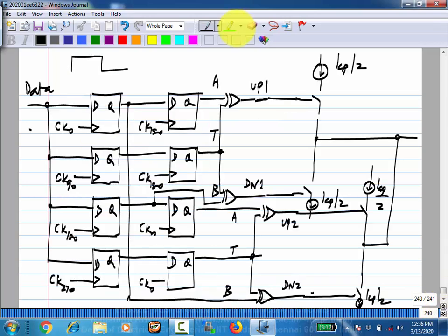Now, if you want to do the logical combination, for instance, if you want to see if up 1 and down 2 are high, you don't want to do anything and use a single charge pump circuit, right? Then you have to delay one of them by half a cycle, right? There is no other way because now actually this up 1 and down 1 are changing at some instant and this up 2 and down 2 are changing at the next half cycle of the clock, right?